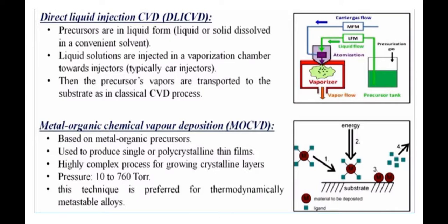Due to that, the liquid forms small bubbles, and then those small bubbles come as a vapor, and deposit onto the substrate surface, and the rest of the vapor goes throughout the chamber. So here two things are there. First, as I mentioned, we are putting the material in a bubble form, and then we are using a certain kind of carrier gas. That carrier gas will carry those molecules to the substrate itself. Then those molecules will react with the substrate, and the rest of the carrier gas will come out in the vapor form, or in the form of gas.